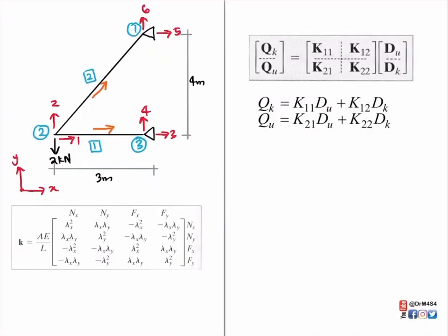Now, refer back to our last lecture. We numbered our nodes, member near and far direction. Remember, we have to number our unknown displacements first. Also, you have to look at what external forces are applied and also the support at each node given to you.